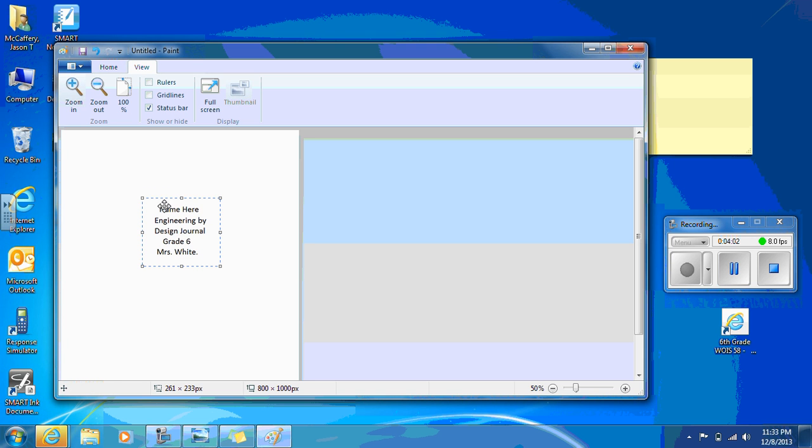If you need to move individual lines, be very careful, but select the line you need to move, as I've done here. Click above, hold, and then drag and click below. And then you may move that line anywhere you need to go. Be careful that when you're moving your text, that you do not select part of your text, or you'll break your text like so. If this happens, press the Control button and the Z button at the same time to undo any changes.